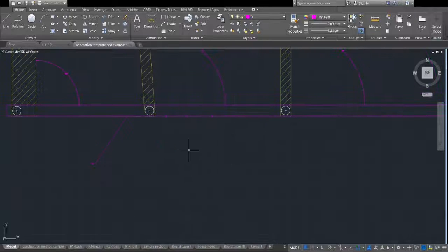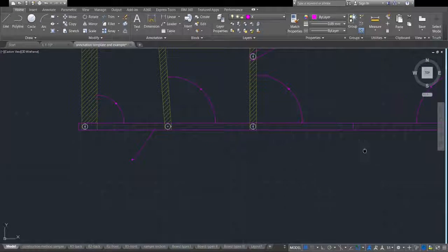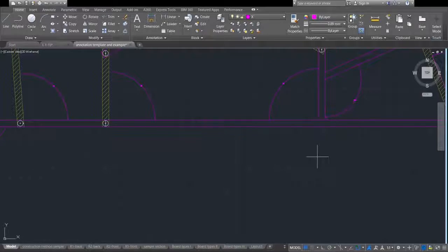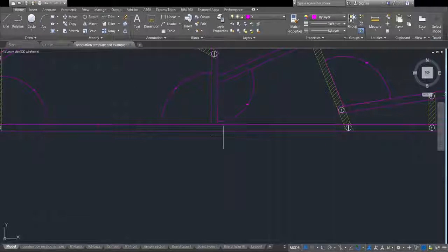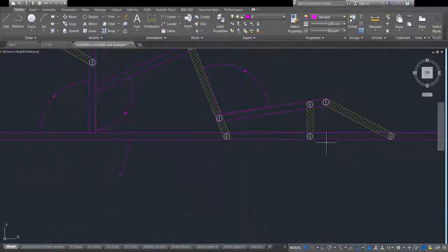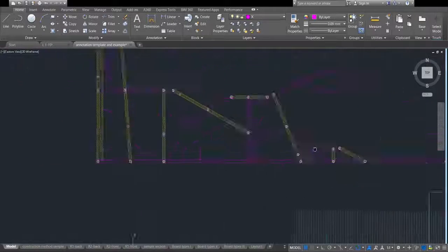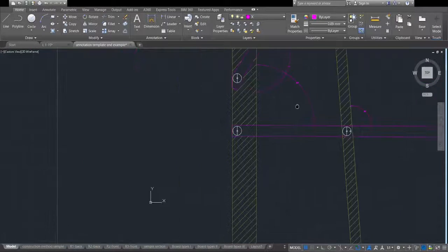You have to use a new command every time you want to put a new line in the annotation, and we only want 1 line. So you just hit enter once to put in the text, and hit enter again to tell it that you're done. Then I'm going to put a new one in, so click, make a new spot, and I type in A, 1B, enter, enter, done. Alright, and we're just going to kind of continue doing that.